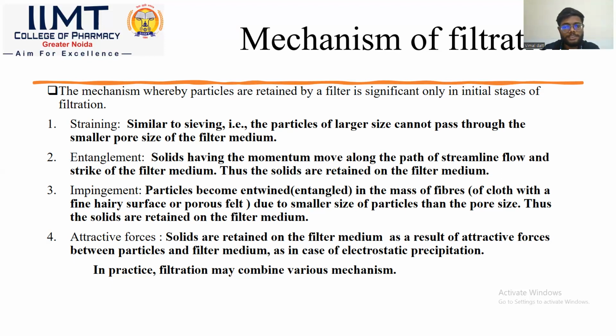And then impingement. In impingement, the particles are stuck in the hairy structure or fibers of the filter medium. And then lastly is the attractive force. These are the common mechanisms used in filtration.